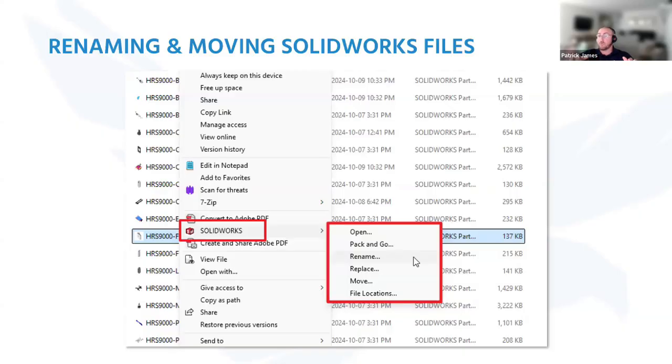It's going to look for bracket one open in memory. So if it's already open in my SOLIDWORKS screen, then it'll look for bracket one in the reference documents folder in my system options. Then it'll look for its last saved, last opened, and a couple of others. And it'll just go through that list. And if it can't find it, then you get that message of, hey, where is this component? Do you want to find it for me?